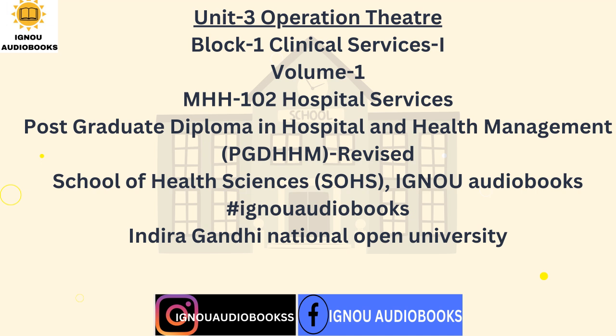Dedicated AHU, air handling unit, for 100% fresh air for each OT, for blow-through system, could be situated on the terrace of the multi-story building above the operating room.